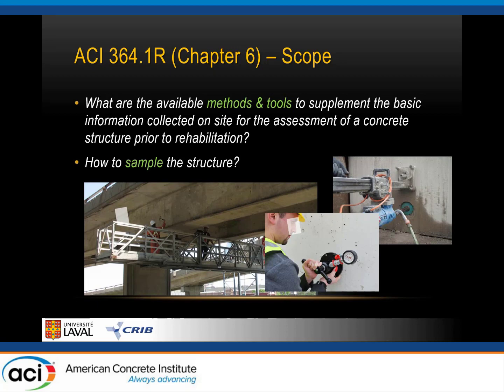So the idea in this presentation this morning is to go over rapidly the methods and tools to supplement the information that we collect on site when performing the assessment of a structure. And in addition to the techniques and methods that are available, how to sample the structure. And sampling does not necessarily mean getting a chunk of concrete out. It's also sampling for NDT, so for non-destructive testing.